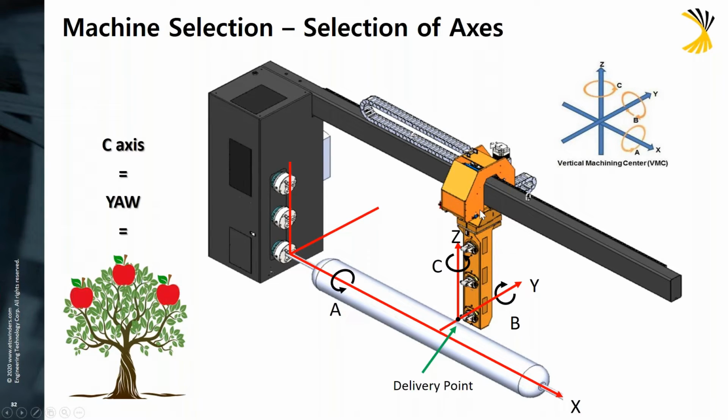The X axis, which is longitudinal down the part and is our main carriage, is usually referred to as the horizontal axis. And these 2 axes give you a lot of capabilities for cylindrical parts, very long, simple parts. But as soon as you start getting into more complicated shapes, i.e. tanks with domes, and you're looking to control your fiber band around the domes efficiently and easily, you need more axes. So we typically add the Y axis and the B axis, which gives you radial motion in toward the part and also a rotational motion of your delivery head.